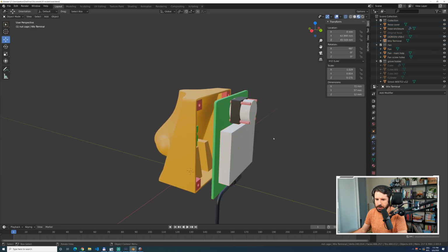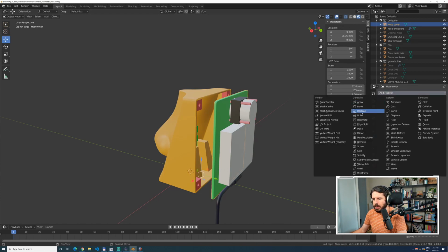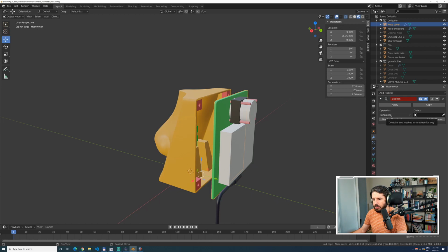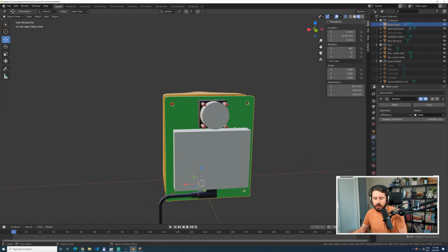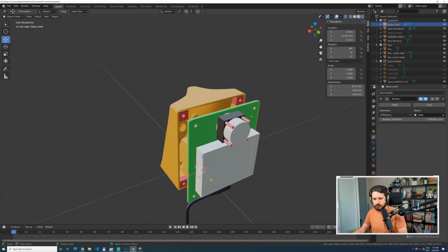Let's bring them just slightly closer so that I can create a hole in the cover by removing the material that corresponds to, where are they? I can select it from here. How are they called again? Nope, that's not what I want. They're called bolts, I think, right? Yeah, bolts. There we go. We have our holes in the cover, well aligned.